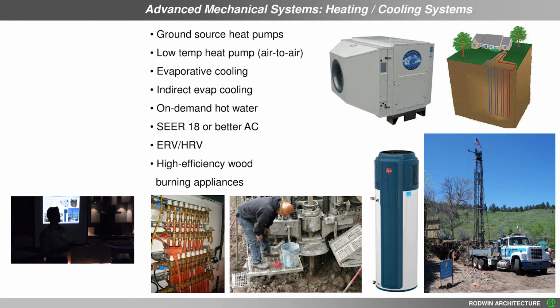On-demand hot water. This is particularly good if you have a very small house, so you don't have much square footage, or if you have a house that's, say, up in the mountains that's a vacation home that you're not in all the time. You don't necessarily want to create hot water and leave it sitting in a hot water tank where the heat just bleeds away for long periods of time. So an on-demand hot water heater is a small device that you can put into a smaller area, and it generates hot water when it's needed and only when it's needed.